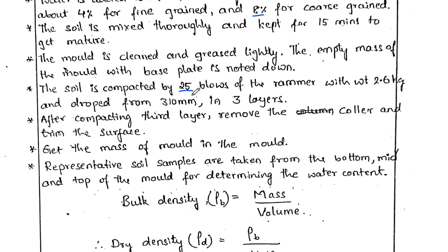The height of drop of the hammer is 310 mm, in 3 layers. The weight of the hammer is 2.6 kg. With a 310 mm height of drop, we have to compact in 3 layers.